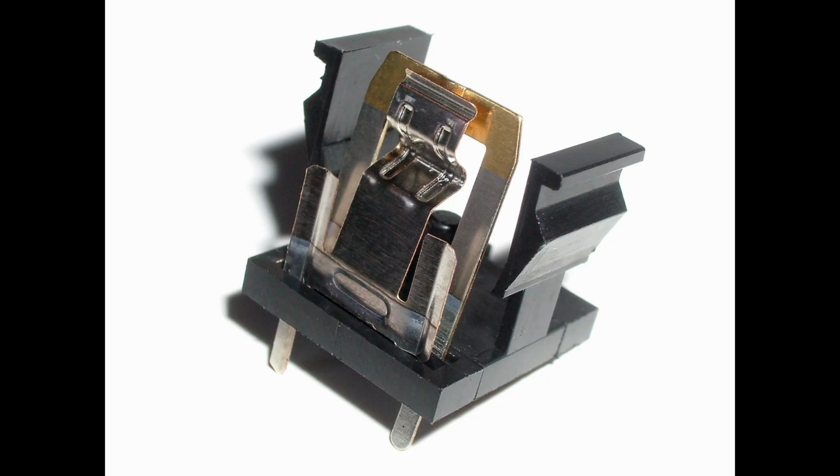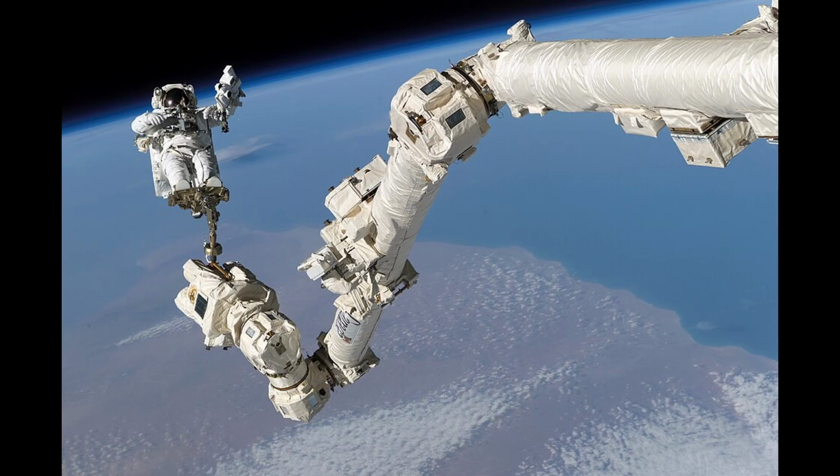One of the simplest devices is a contact sensor. This is simply a switch, which is open or closed depending on whether the device has come into contact with something physical or not. For example, a robotic arm may have a limit to its motion around a joint. So adding a contact or limit switch could signal that it's reached its maximum displacement.